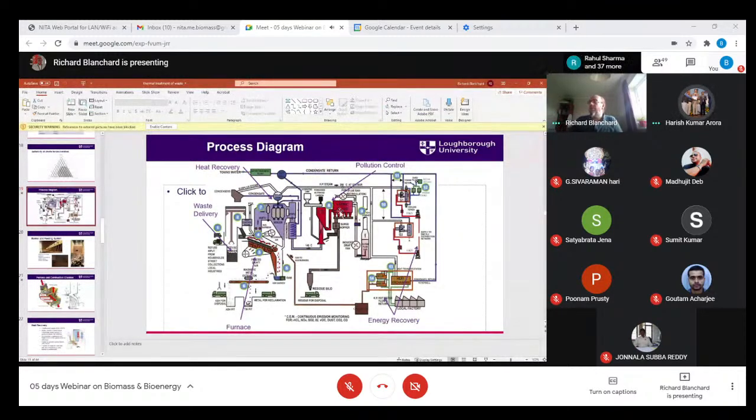So a fabric filter has to be provided. Yeah. And this is in the middle of the city, in Coventry. So the first stage is to treat the gases. We add lime to get rid of the acidic gases, and we add activated carbon to get rid of any organic compounds which might have formed, like furans and dioxins. It then goes into the treatment stage, getting rid of the particulates, and then goes out of a chimney. Thank you very much.